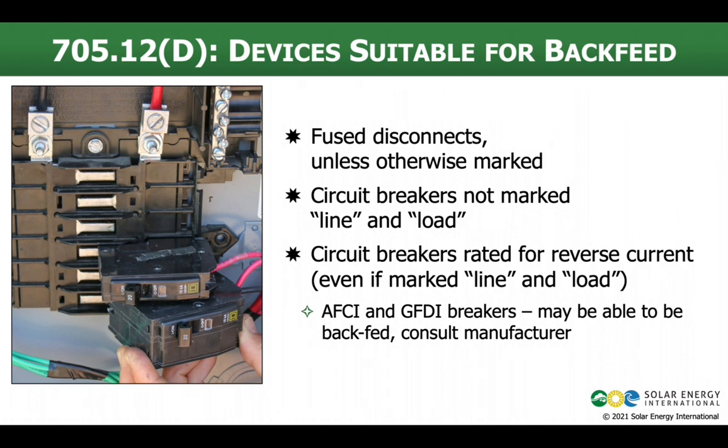And that may limit how you can interconnect. You may have to be connected on the supply side instead of the load side, which could be more expensive. So always talk to the manufacturers of the specific breaker that you are concerned about when it is marked line and load. It very well may be okay. You just need to get approval for that.